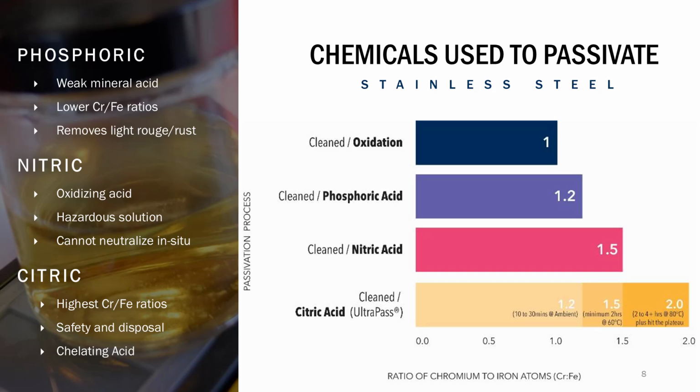Nitric acid is probably the original acid that's been used. What is nice about nitric is that its parameters are quite easy. You run it for around a half hour with no added temperature. It's pretty difficult, or unsafe, to put temperature into nitric acid. You can evacuate a room if you get any higher than around 140F or 60 Celsius.